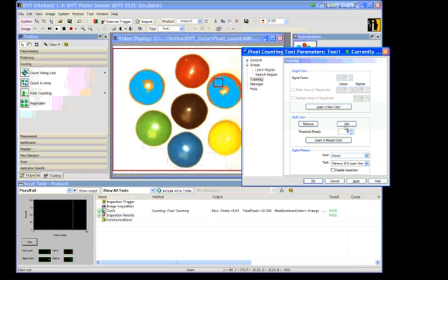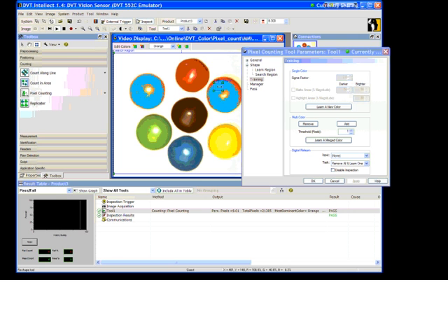We can change that threshold so that we set it to 1. We basically learn every single color that is present. When I say color, I mean RGB combination that is present in our learn region. So if I do add here, basically I learned everything that was there. You see the image marking, basically we inferred the color so that we can look at that.